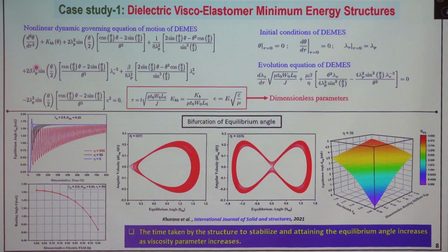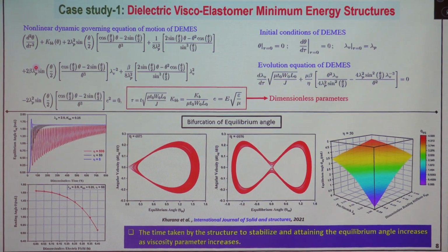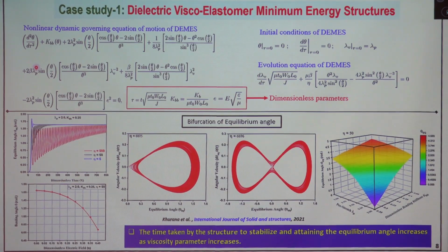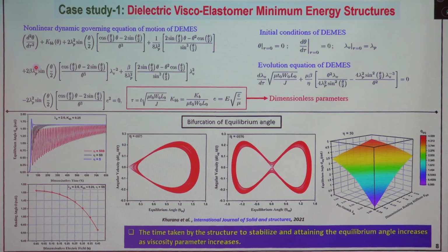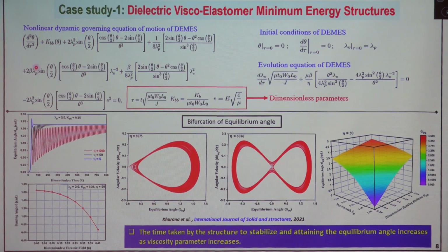So we have already seen that there is some truncation error of dt order, where dt is the time step. So it is an RK method with a truncation error of dt to the power 5. That's why it is called ODE45. Different solvers are there. An RK method of second order is also there, and in that case it has a different name, depending on how much truncation error it takes into account. So MATLAB has different solvers, but this ODE45 is an effective solver which can give very good results when you implement it. Okay, I will show you that tomorrow.